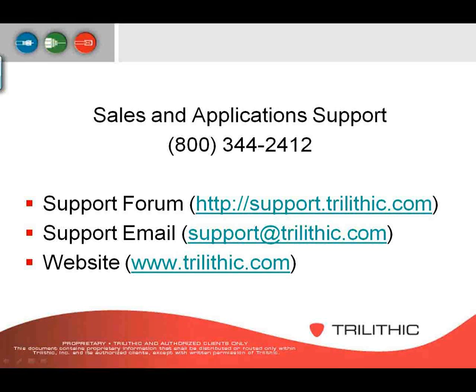Is there a simple method to figure out what the MER should be in relation to the digital level and where the cliff effect is? The only thing I can say to that is that when you start getting below 30, that's when you're going to start having problems. Depending on what set-top box you have, there are different thresholds for where you'll actually have the true cliff effect. It can vary, but just remember, if it's less than 30, then you want to be prepared that you could start getting a cliff effect.